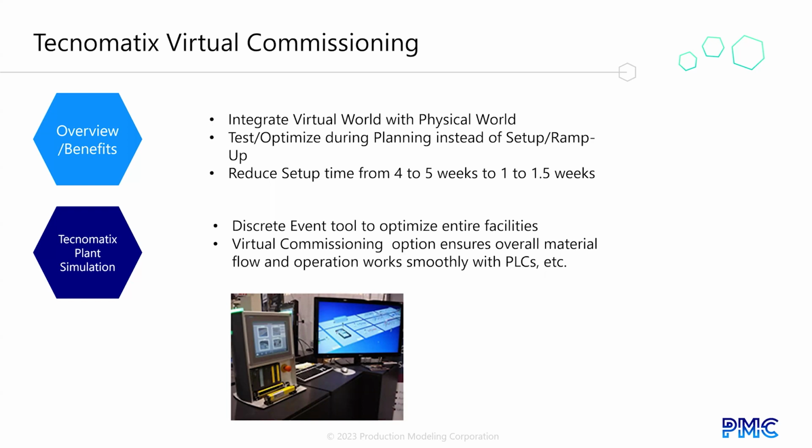But when the plant was built, deadlock conditions ensued where everything was stuck. The problem was that the simulation implemented slightly different control logic, so the problem didn't occur in the simulation. Now they can interface PlantSim with the PLC so that the exact control logic from the PLC controls the simulated stops on the conveyor to ensure accuracy.